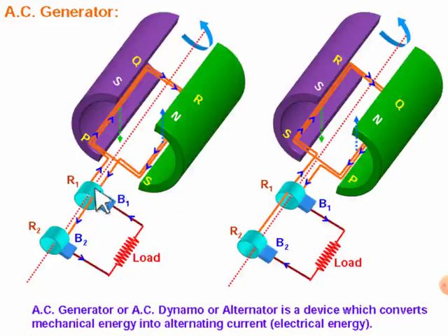When the armature is rotated, the slip rings will also rotate with it, but the brushes will always remain in contact, so that there is always an electrical connection between the slip rings and the brushes. So the current can be taken out from these two terminals across this load resistor. One will be connected from here, another here. That will be the output of the AC generator, right?